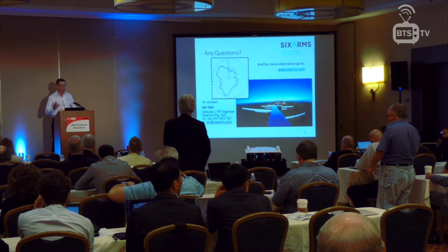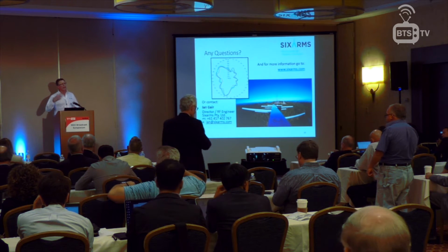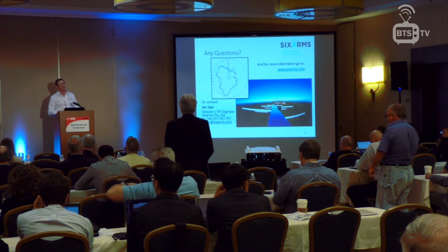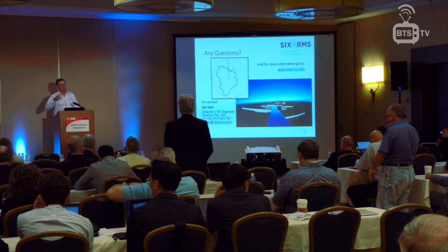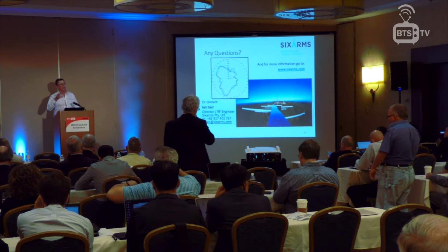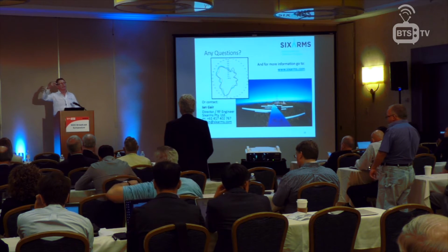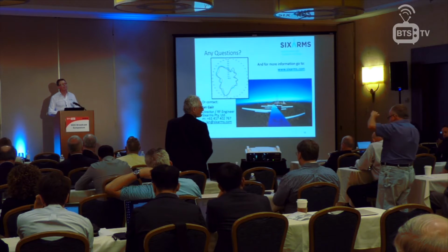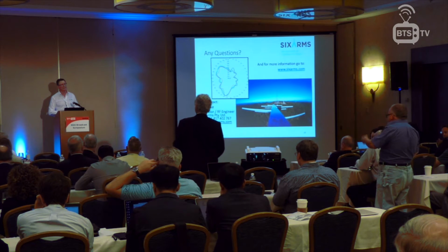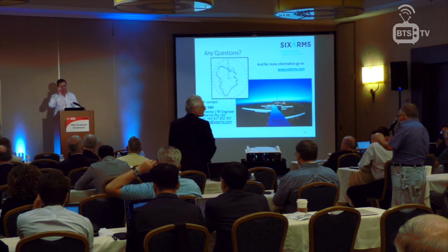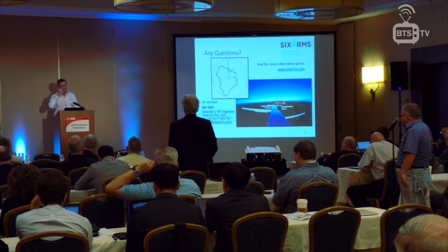Yes, the concept of doing this is to check whether it's as per the design. If the design hasn't been implemented, for instance with a panel upside down, you'll have some effect that shows in either the HRP or the VRP. I've heard of cases where a pylon slotted antenna, UHF, was rotated 180 degrees out, and I'm sure we could still find that with a close-in fly.